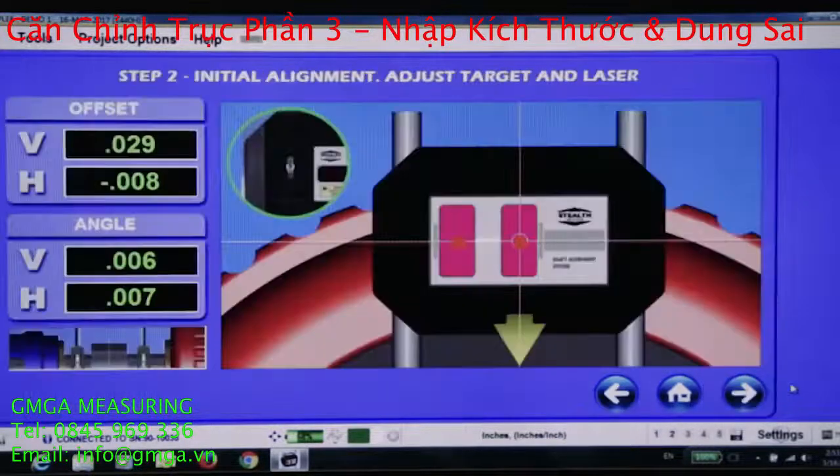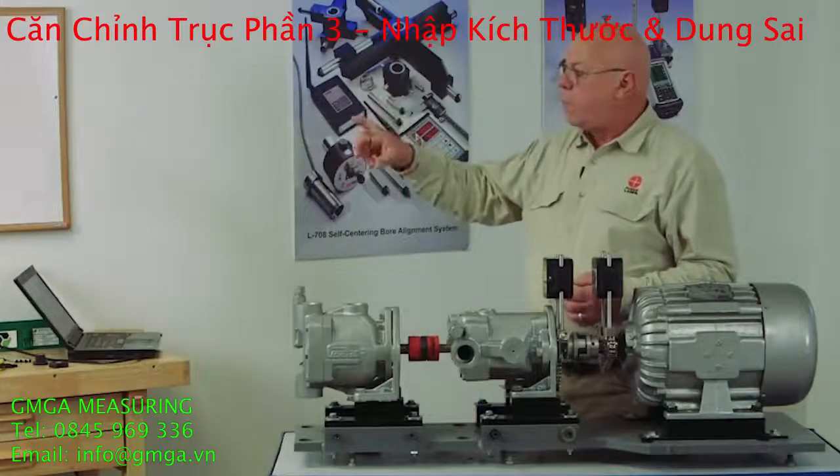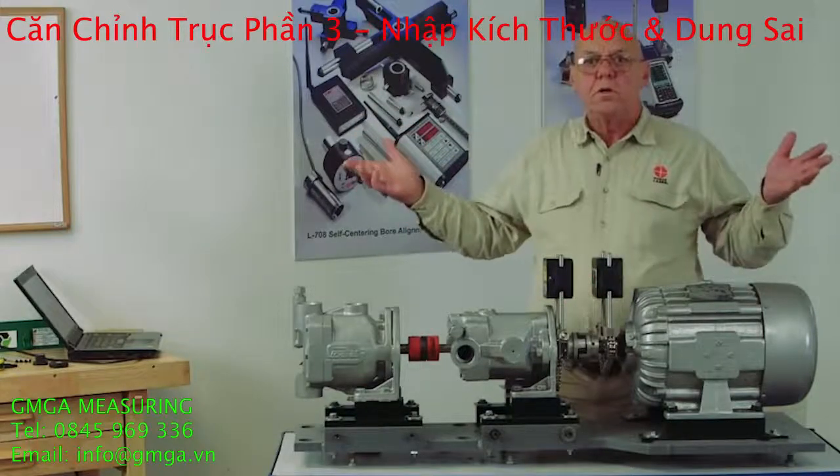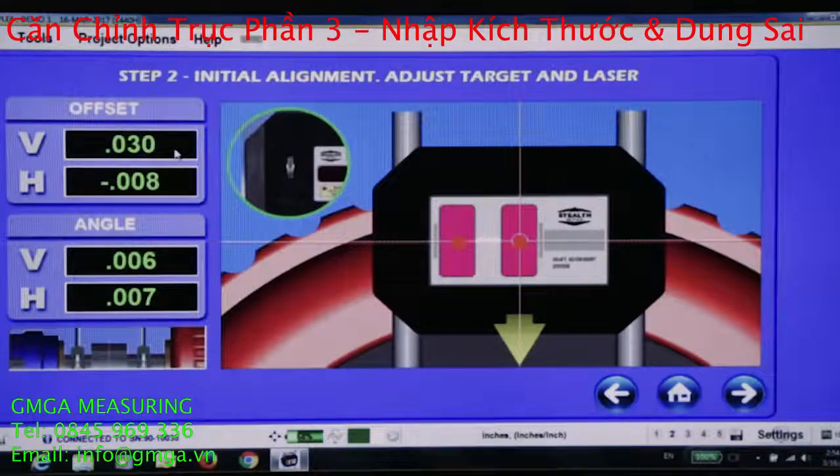When I get to the data taking screen, I'm sorry, this is still course alignment, but you see here, all I did was align this with the cover on there, with the 2 little holes, and I'm good. Those numbers are green. Now, this is showing me I need to take that target down just a little bit if I want to get better than 30 thousandths. 29 thousandths is good enough, but if I don't like that, I can loosen this and I can lower this down until I'm closer to 0. Once I get that close, the arrow even goes away.